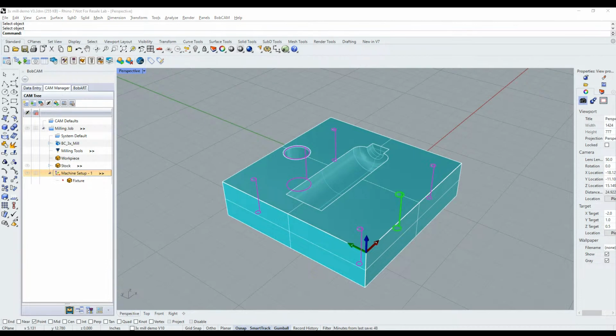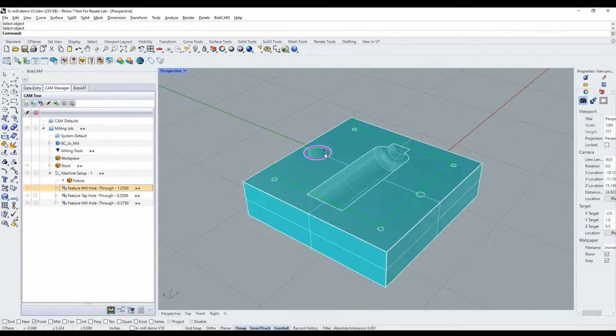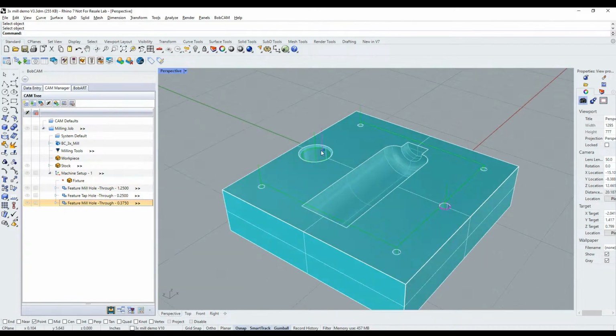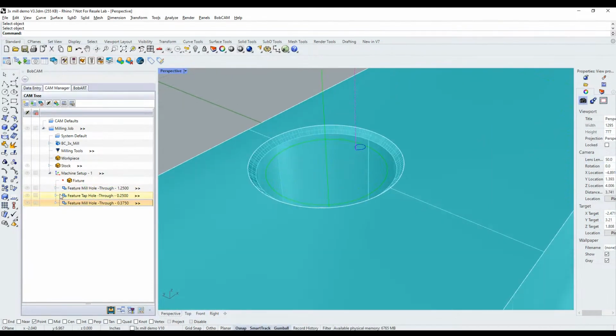And then for drilling, we can tell the software whether we're only doing drilling with the hole option, tap hole, counterbore, or counterbore tap hole options here. So if I wanted to do a tapping operation with the 1/4-inch ones, for example, I'll drop that down and select tap hole and then hit compute. Then we've got the 3 features already set up here in the CAM tree automatically. We've got the 1/4-inch hole to start with, and the 1.25 inch, and then the 4 1/4-inch holes, and then the one at 375.